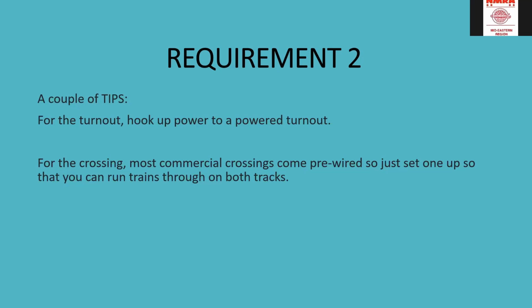A critical thing when running trains through these devices: for example, on a crossing, it's a good idea to use a longer wheelbase locomotive than a short wheelbase, so that if you have an issue with power, like in the exact center area of a crossing where we can't have power, because if we do with DC or DCC, we're going to cross something up and cause either the phases to cross or have a positive and negative thing that cause a short, and it's not going to work.